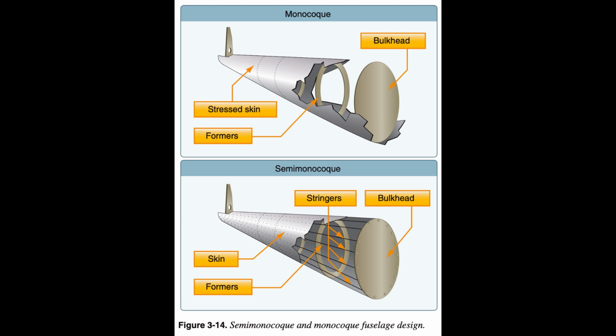For example, an aluminum beverage can support considerable forces at the ends of the can, but if the side of the can is deformed slightly while supporting a load, it collapses easily. Because most twisting and bending stresses are carried by the external skin rather than by an open framework, the need for internal bracing was eliminated or reduced, saving weight and maximizing space.